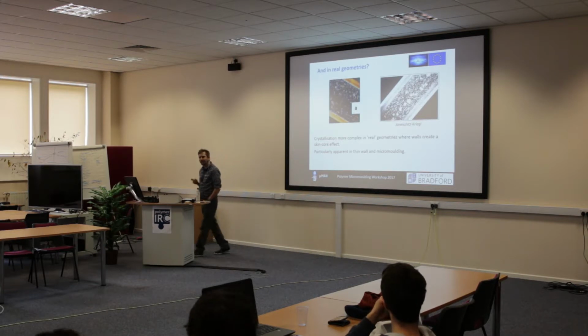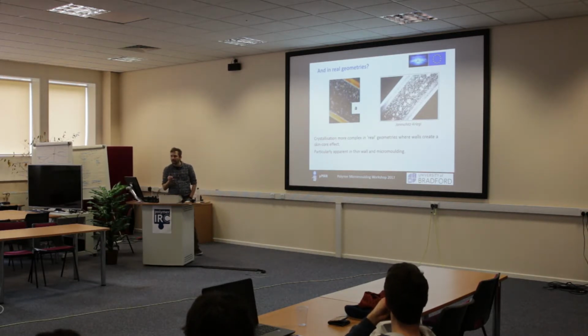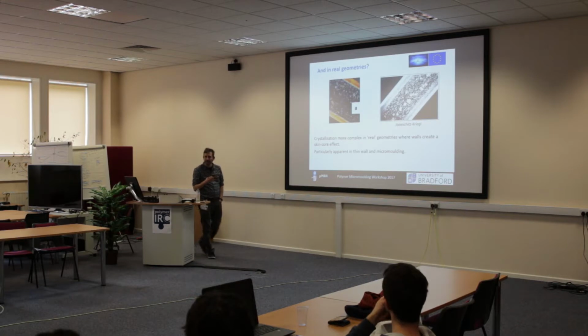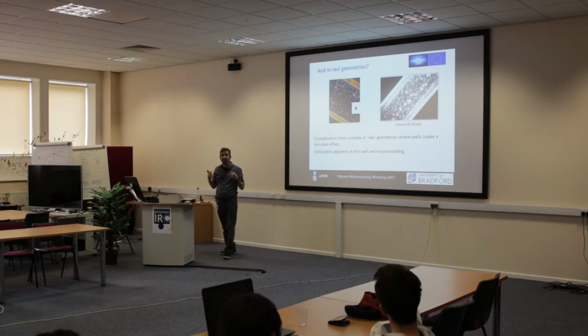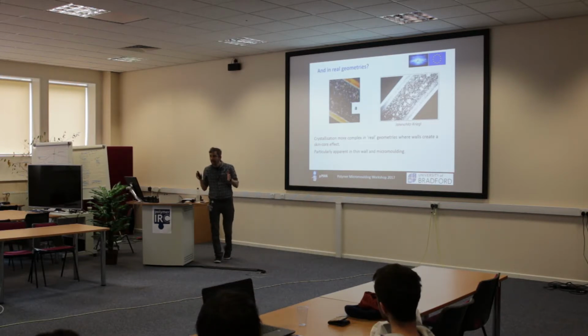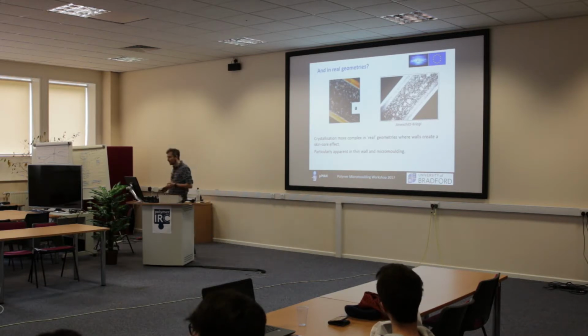If you look at your flow, and I'll come on to flow very briefly and how rheology impacts on this, then your shear rates are greatest at the wall, okay, because of the no-slip boundary condition. Like the velocity of the material nominally needs to be 0 on the wall.